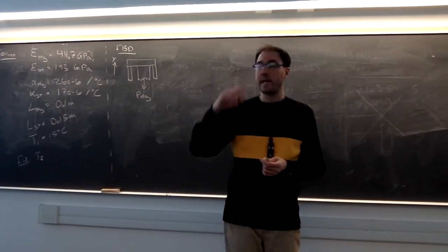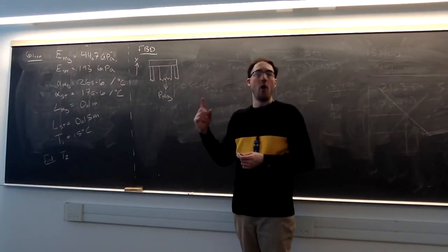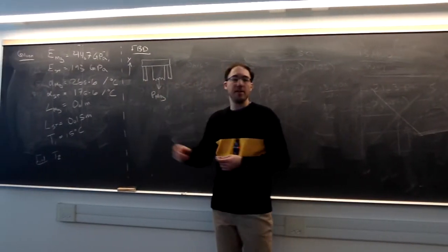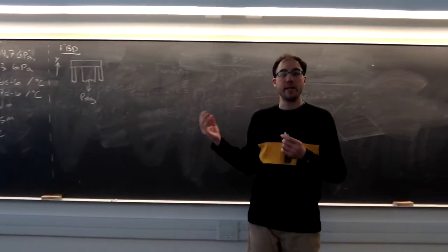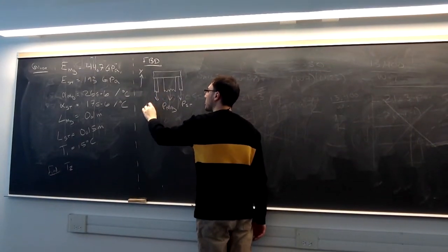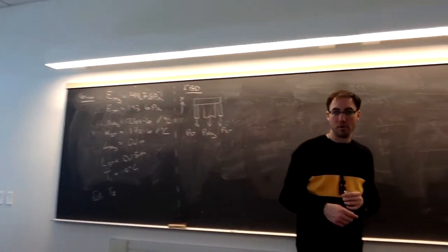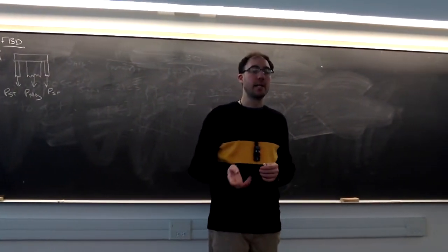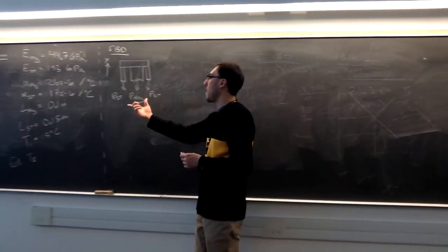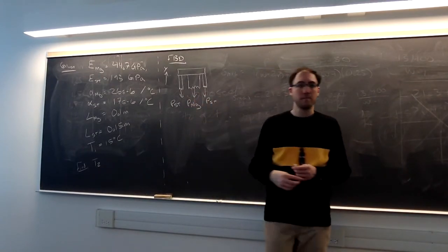What this is going to affect is if we treat it as one collective material, we have one force that's the force in all of the steel. But then the area is the total cross-sectional area of the steel that we're talking about. Or we treat the steel individually, which is how I did in my notes. But now the cross-sectional area changes because now it's only the cross-sectional area of an individual bolt. The end result will be the same because either I'm doubling the force and also halving the area, or I'm doubling the area, but I'm only having one force I'm talking about. So the end result is the same as long as it's symmetric.